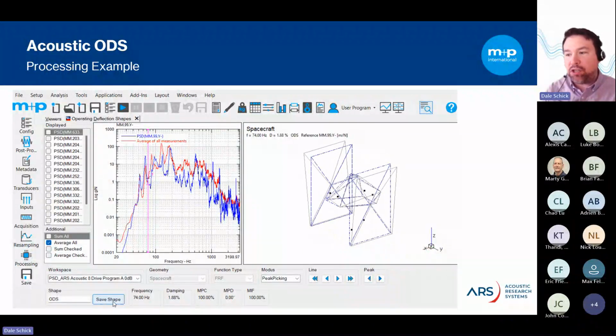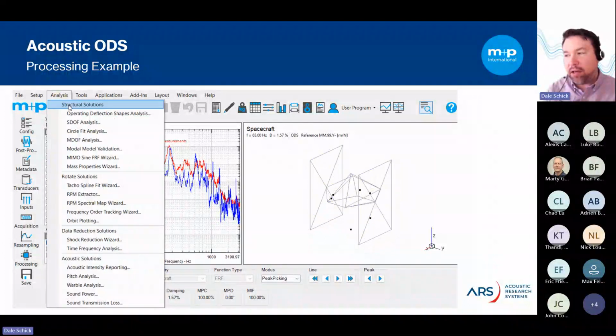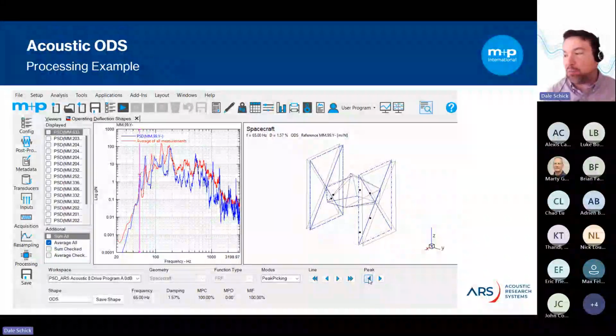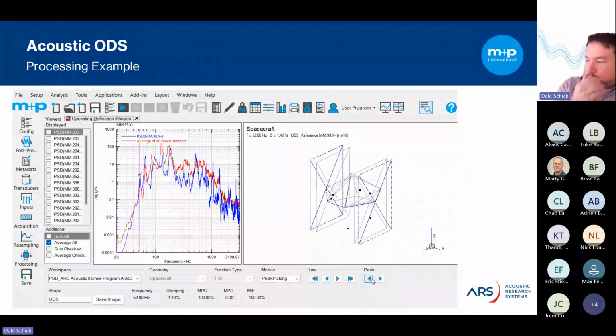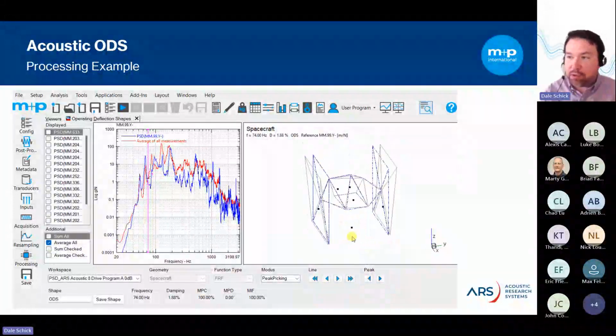Once we have all those mode shapes in the software, we can simply export all of them to UNV or UFF, and that could be applied to a finite element model system so that you could possibly correlate some kind of predicted responses. We actually wrote a paper a while back where Wave6 did just this with a known panel of a known size.